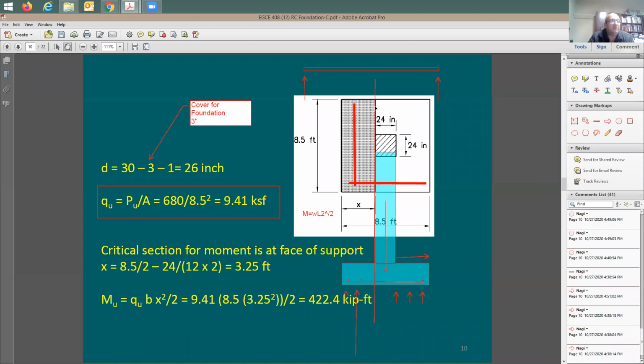This force is going to be equal to this pressure below the footing, below this shaded area, multiplied by the area. And the moment arm in this case, from here to the section, is going to be equal to X over 2, or 1/2 of X. Why? Because this force happens right in the middle, right? Which means you're going to have your X over 2, and the force is right in the middle. And then you say, this force multiplied by X over 2. So someone is going to take the entire pressure, multiply it by this contact area, find out the force, and multiply by X over 2, which is the same as this equation, by the way. So this equation is going to be the same thing that I'm doing here.